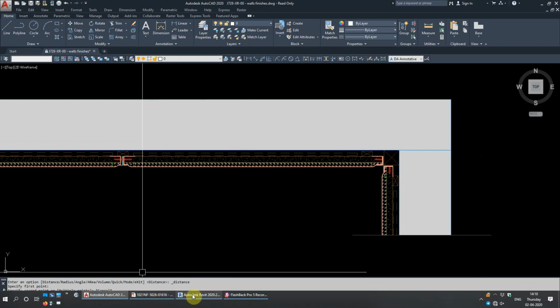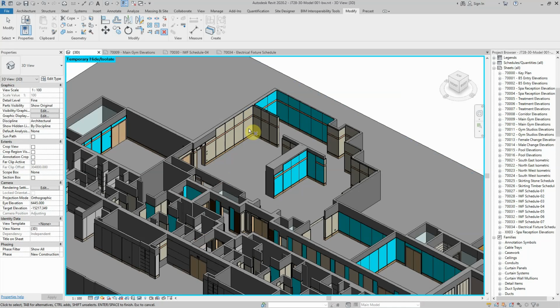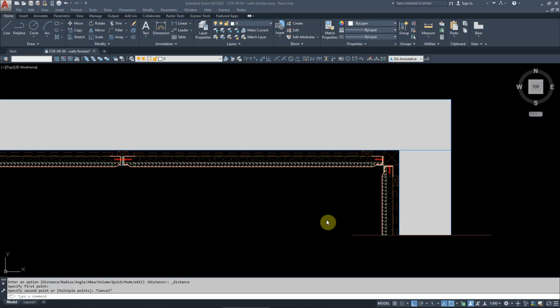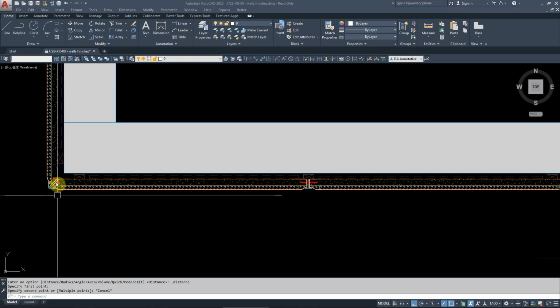Then we go back to Revit. We put the first panel in, then we put the second panel in, and so on. We realize that this trim here is going to be 25 mil, and this is going to be 10 mil on the side, because this panel has to have 10 mil on either side. You see 20 mil in elevation. So you slowly build the thing together. You come to the corner and you realize that you have to do a special type of trim. You go back to AutoCAD, and in AutoCAD you design a special trim.